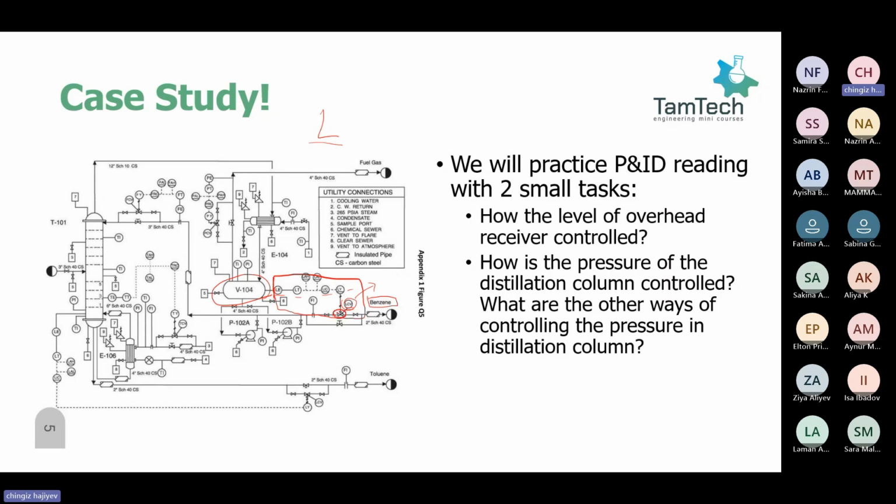And using this valve, if we increase the flow of benzene, so-called, if you open the valve, then the level will decrease, because you see we have a control connection with this valve. And if we do vice versa, if we close the valve, then we have an increase in the level.